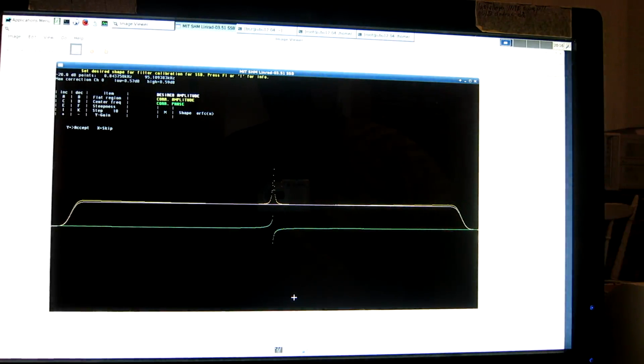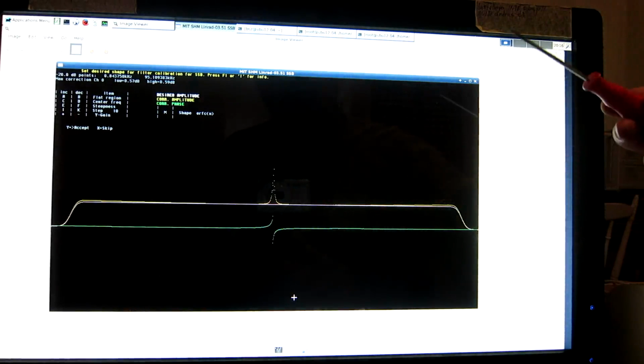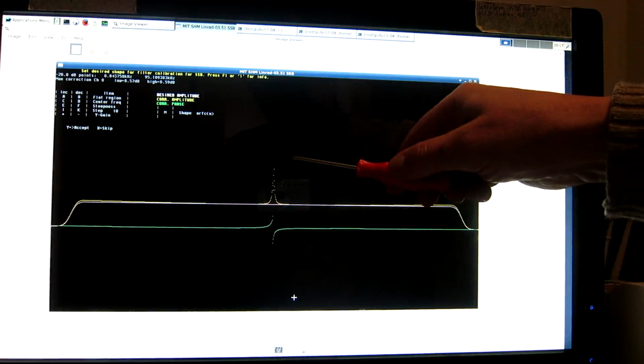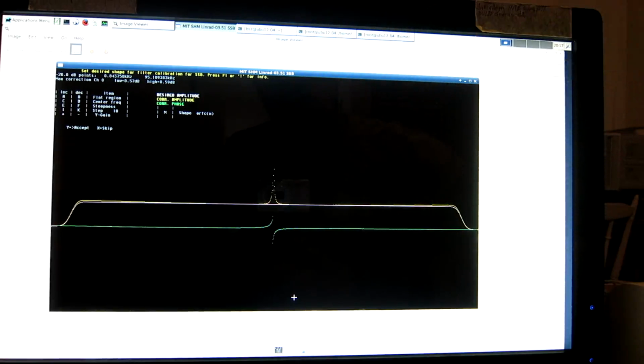for perfect operation. We can see also the yellow curve that shows the difference between the amplitudes we actually have and those amplitudes we need. And of course, at 0, at DC, this is infinitely high. That's absolutely not acceptable.